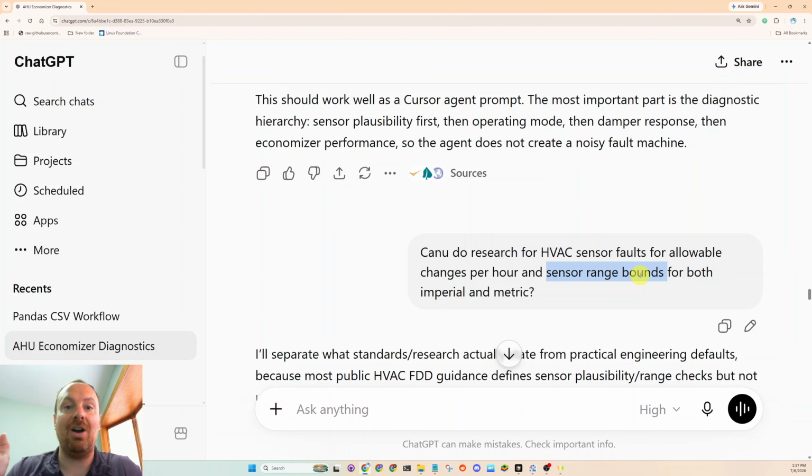It should be caught on the building automation system alarming, but half the time what happens in building automation systems is the alarm console turns into the little boy that cries wolf. There are so many alarms happening, people just ignore it. I would bet on making money that most buildings have an alarm console that's been neglected. It hasn't been maintained. I would bet heavily that is usually the norm. The alarm console is a service. It requires active servicing.